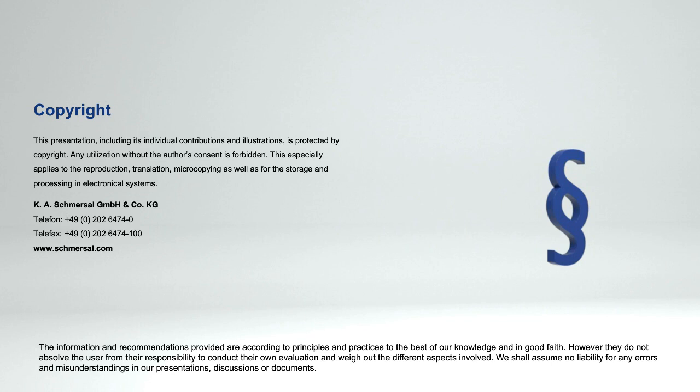So that's just one example, but that's what we mean by fault exclusion. It's the possibility of a fault that may still occur, but we can exclude it as a likelihood because of these reasons. You cannot put fault exclusions in the system out of convenience. Fault exclusions need to be justified, because what you see sometimes is, oh, you know what, I can't do that, I can't test for that, so I'm going to list that as a fault exclusion. No, that's not justified. That was convenience. You're just trying to avoid some work there. How can you exclude it as a potential fault?